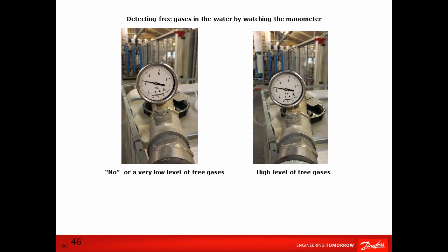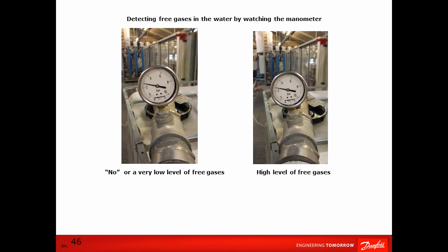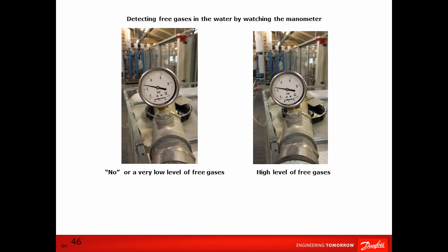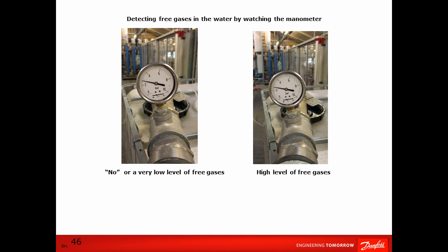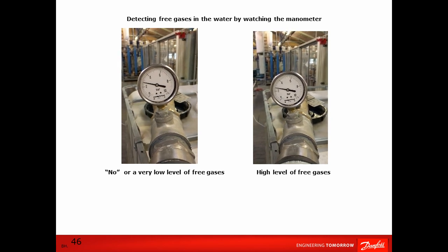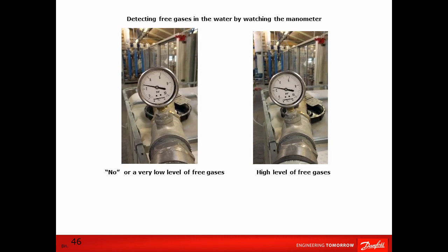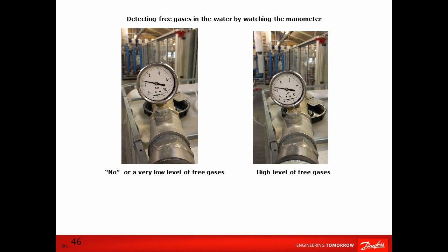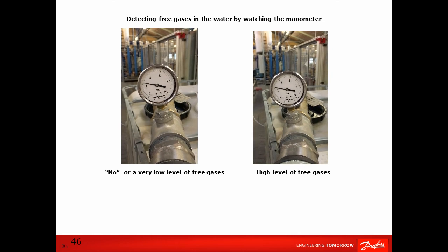If the high-pressure pump fails due to cavitation before the scheduled service inspection, check inlet pressure and temperature. If these values are within limits, compare the pistons of the defect pump to the other pumps in the system. If the wear of the piston slippers exceeds expectations, open the pump and look for cavitation damage inside the pump. If you find cavitation, it has most likely been caused by gas bubbles released by the feed pumps.